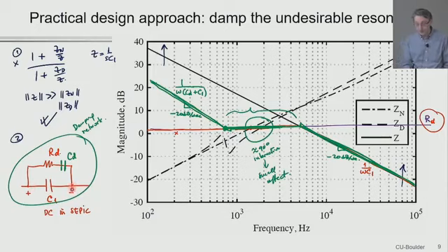The closer the voltage across C1 is to DC, the less dissipation you're going to see on RD. Another alternative is that one can add an inductor in parallel so that it also looks inductive as ZD. And in that way, the converter doesn't work, right? If you put the inductor in parallel right here? Yeah, and you have no phase, they are both inductive. But just putting an inductor in parallel with the C1 is going to be a DC short, so that's going to totally destroy the converter.